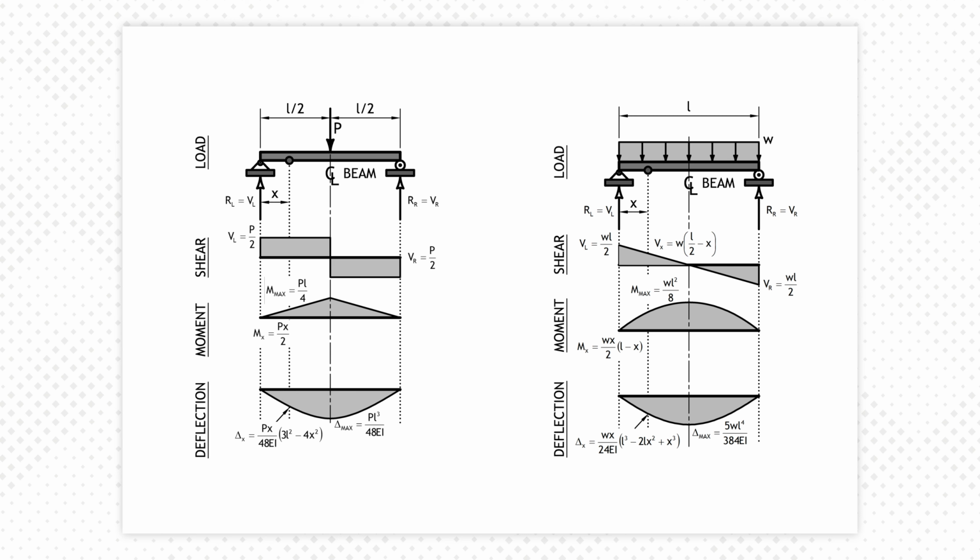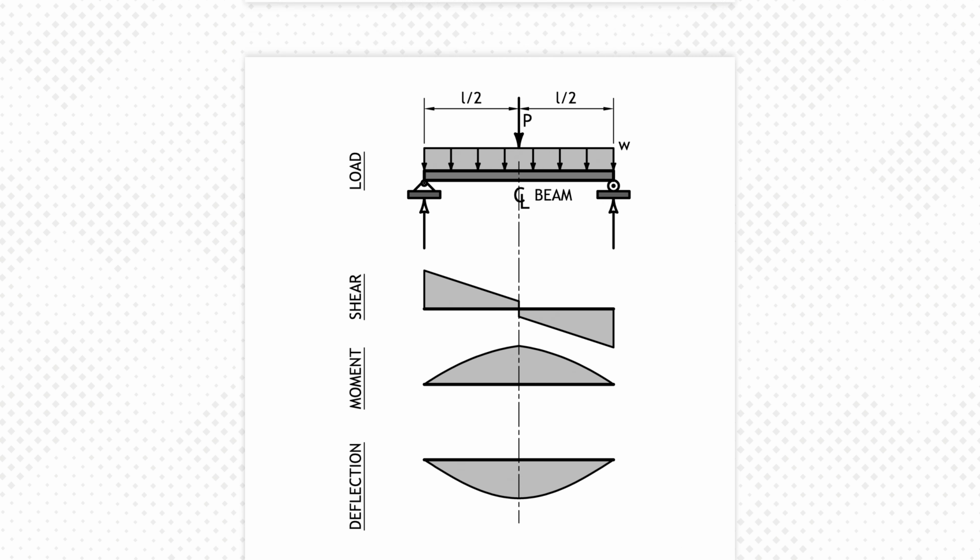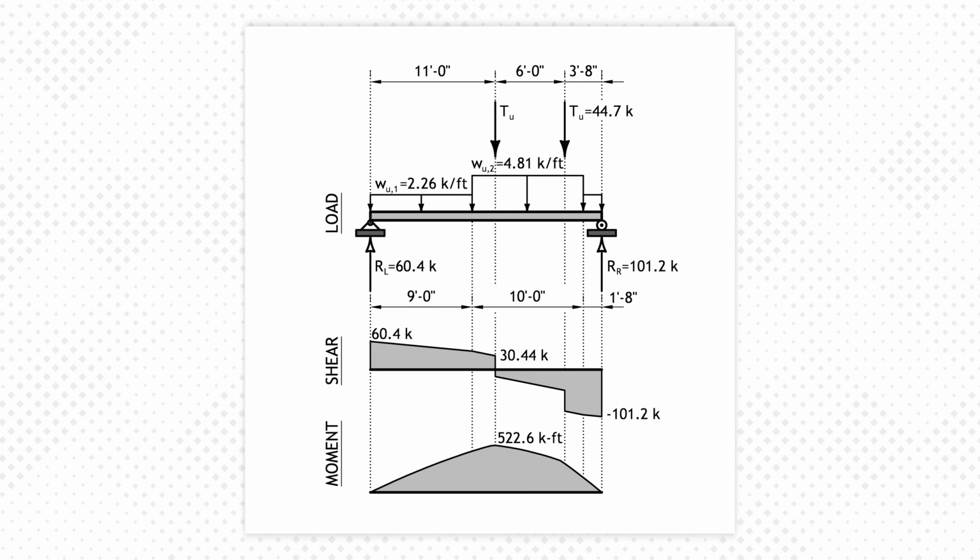For simple beam loading, a wide variety of formulas exist that provide shear, moment, and deflection at any point along the beam. For linear elastic analyses, we can superimpose these beam solutions for combined loading. This can provide a nice check on software. Shear and moment diagrams plot the load, shear, and moment along the length of the beam. We can solve any statically determinate beam this way.